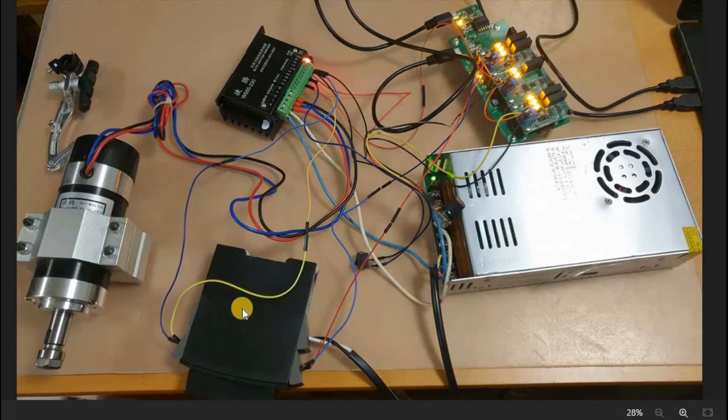That will go to this signal conditioner, which will convert it from frequency back into 0 to 10 volts into this input module on the evaluation board. We also have a potentiometer here, which is going to be used in order to generate the set point for the motor controller later on. And lastly, we have here a bike brake, which we're going to use to press on the motor in order to see how the fuzzy controller is going to respond to some load or disturbances and what have you.